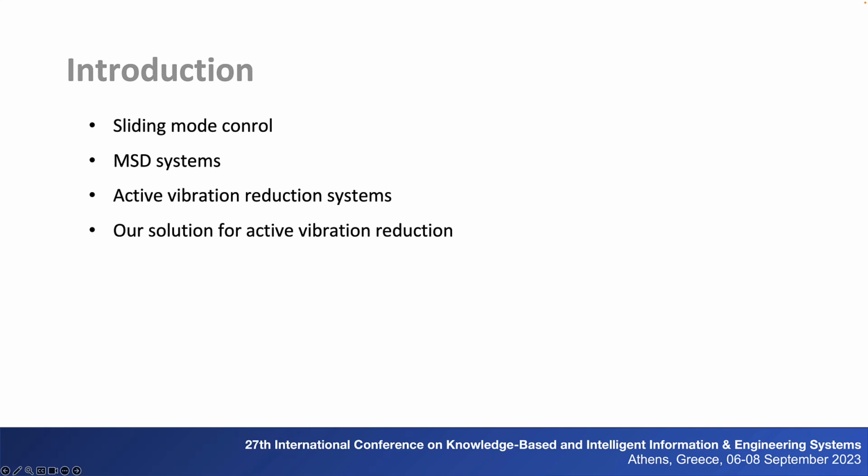In recent years, the permanent magnet synchronous motor, PMSM, has emerged as a popular choice for many mechatronic systems because of its several advantages. PMSMs have a high efficiency due to their permanent magnets, which provide a constant magnetic field without the need for high energy consumption. Such actuators have a high power density due to their compact design and high torque-to-weight ratio. They can operate at high speeds, making them suitable for use in high-speed applications such as automotive. Moreover, the PMSM motors have low noise and vibration levels since their smooth operation and absence of mechanical commutation.